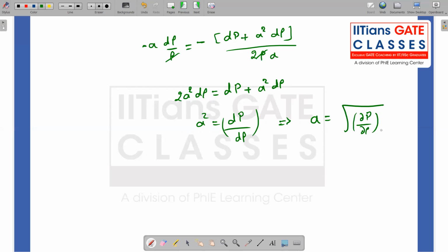So I have to treat it in a very general way. And I know the speed of sound is following, the sound wave is propagating such that it's following an isentropic process. So at constant entropy, this is my expression for speed of sound. But how can we relate it to temperature? So that's what we started off the questioning.